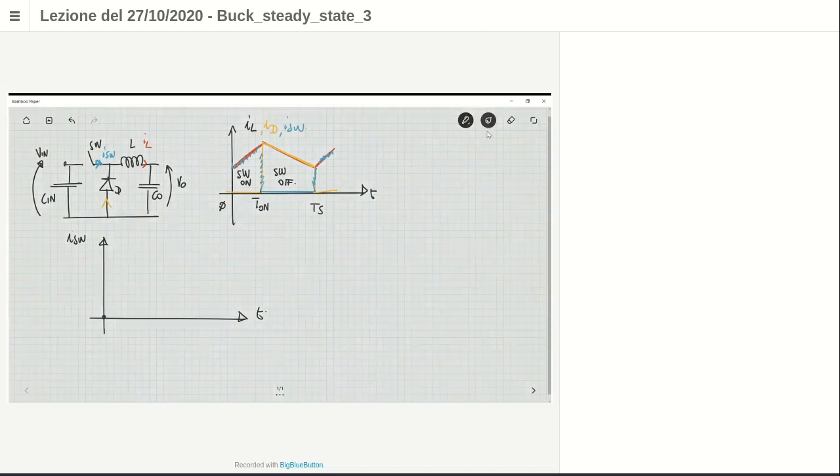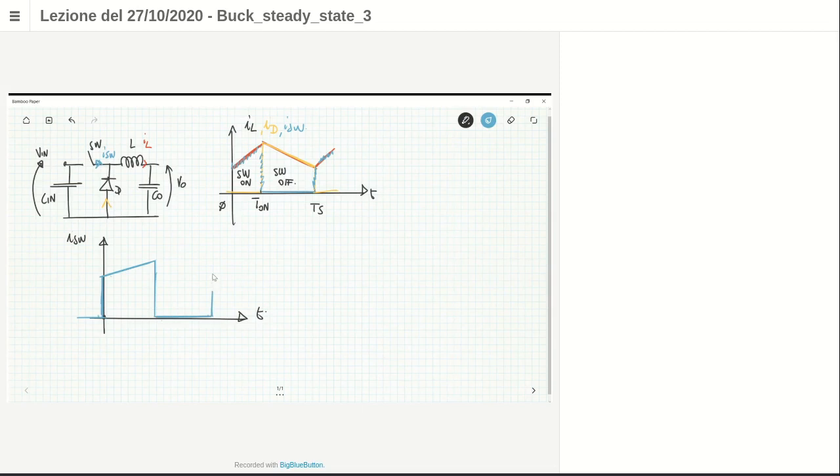So the switch current, this one. Okay, the switch current is the current flowing through the MOSFET, because we typically use, in a modern power supply of say less than 1 kilowatt of output power, MOSFETs. They are the transistors that you can use. They are faster than other devices, so typically you can use any MOSFET.